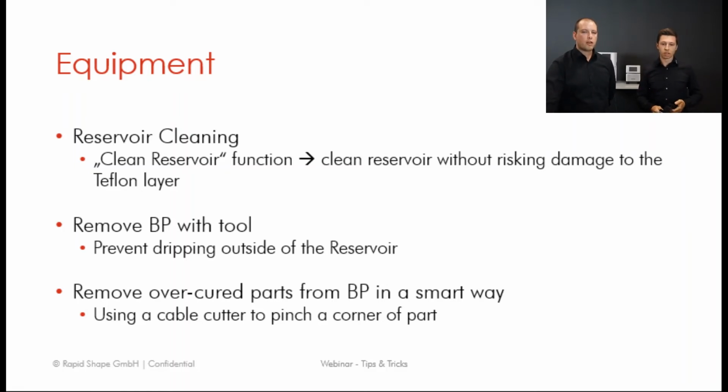So this can also happen during shipping, because of vibrations that are involved. So during an installation, ideally the limit switch should be checked with the build platform inserted with the calibration plate inside, and so on and so forth.